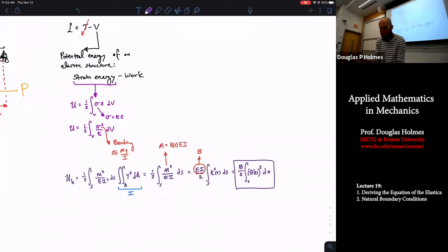What does that mean? How does that help us? So now we're going to look at the work. If I redraw my object over here, here's my length L. If this thing is inextensible, then as I buckle this object, the length of my bar is not changing.